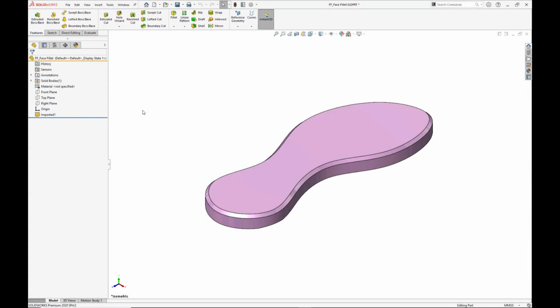Okay, for this next one, this is actually a great application for individuals who want to use curvature continuous. Much like how you can drive it when you're creating splines at the sketch level, if you ever run into situations where the tangent continuity between the default fillet and the adjacent face creates a noticeable break, and I'll go ahead and generate one fillet just to show you, you can use a curvature continuous function.